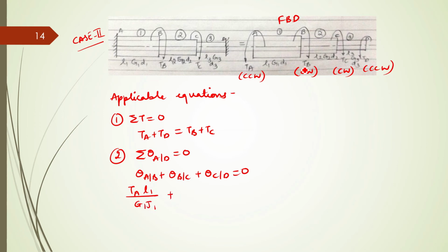For the second portion, now when I calculate for the second one, I will suppose stand at junction B. Already at junction B there is a torque TB which is acting, and the other one is going to be my TA whose effect I am going to consider at point B. Now they both are in opposite direction. So let me assume that TA is greater than TB.